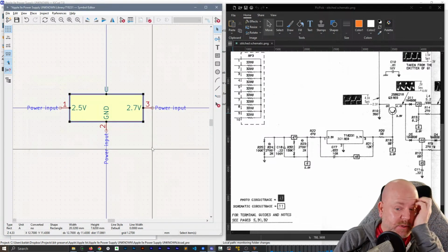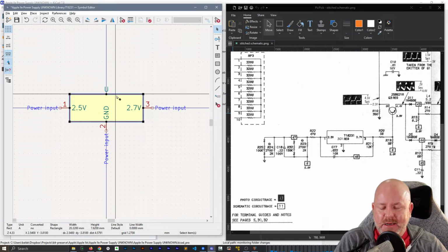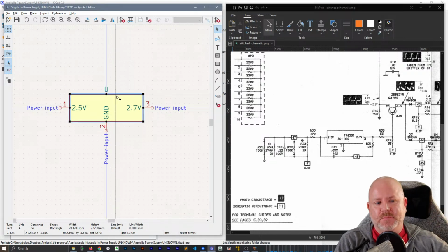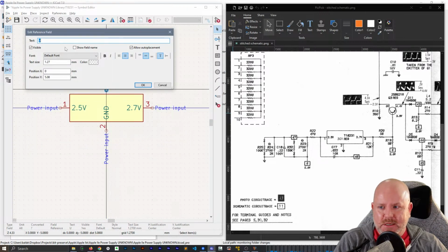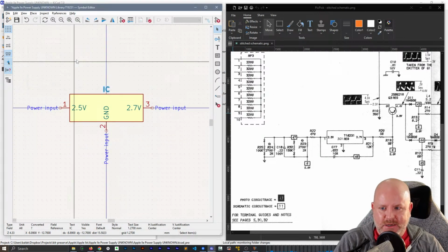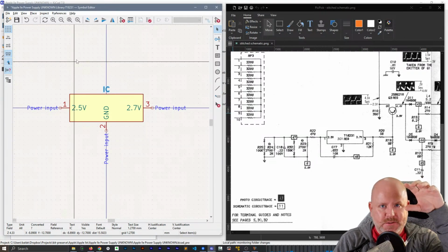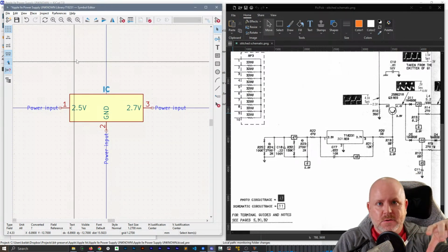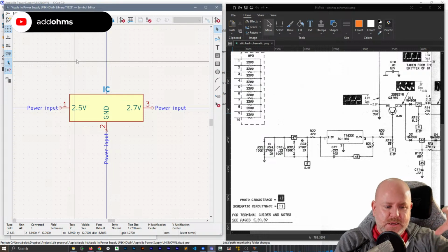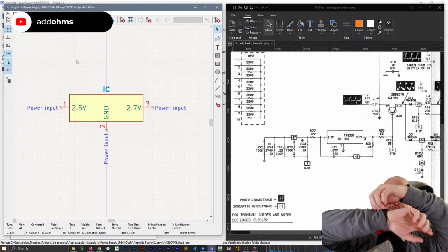I just make that distinction because a very common thing I hear is somebody will say, I need a PCB that does something. And that's the wrong approach. What you actually need is a circuit that does something. And before you get a PCB, you need to design a circuit. So once you know how to design a circuit, then you can draw the schematic for that circuit. And then from there, you can design a PCB, right? You design the circuit first, and then you do the CAD work to make the circuit board.